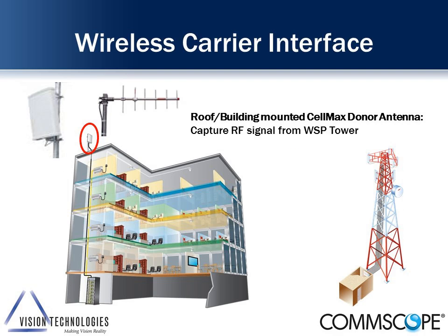So the first option is basically putting an antenna on the roof, pointing it towards a cell site, and bringing that signal in from the outside network, which is referred to as the macro network. Please be advised, though, in this particular case, many enterprise clients think that they can put one antenna on the roof and bring the signals in from all the carriers, and it doesn't work that way. We would need to have donor antennas for each respective carrier. So that's a very important consideration. And keep in mind also that we're sharing the signal with the outside network.